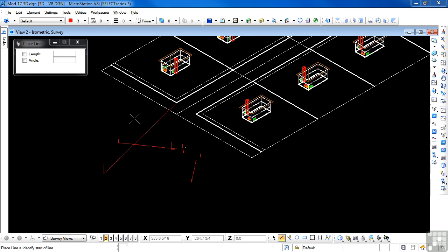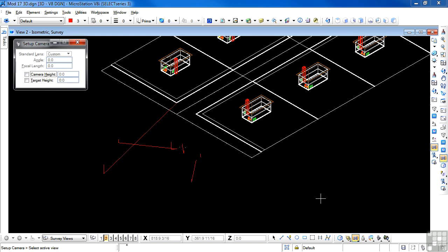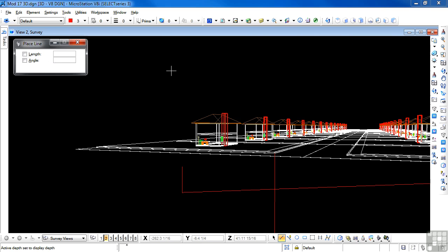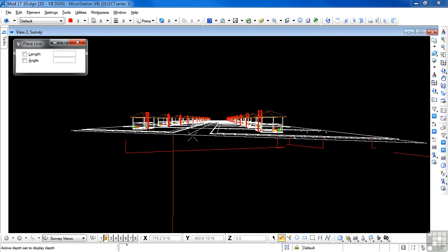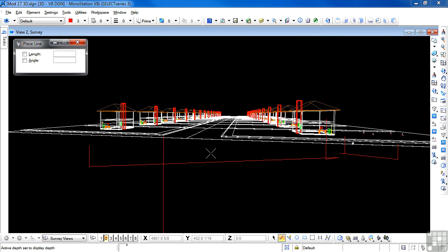Okay, now let's add the camera. So camera tool, data point in the view, wide angle, location of the camera, and probably halfway up the building. There we go. Now we're all set. With that in place, we can start working on our sun and our fog, which I'll do in the next video.